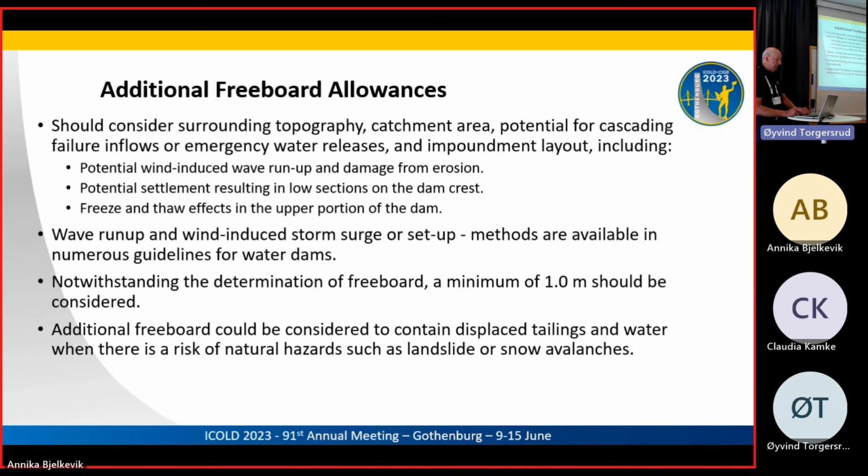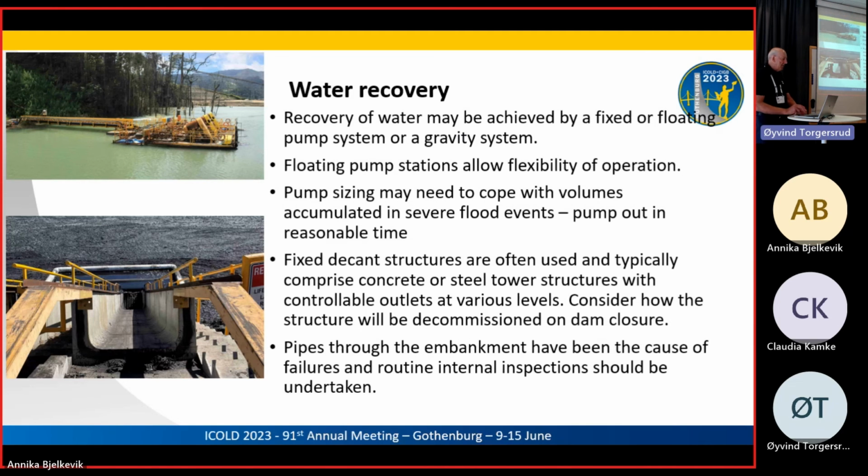So you need to think about whether you need any more freeboard and how that would be achieved. Water recovery can be by fixed or floating pump systems, or gravity. Mostly we're getting a lot more pumps these days, but you need to be careful that we're sizing these for the same thing that Malcolm raised earlier. If we do get storm events, we have to plan how to get them out. So removing the water after a flood could be the design parameter for the pump station or the decant, rather than the day-to-day operation.